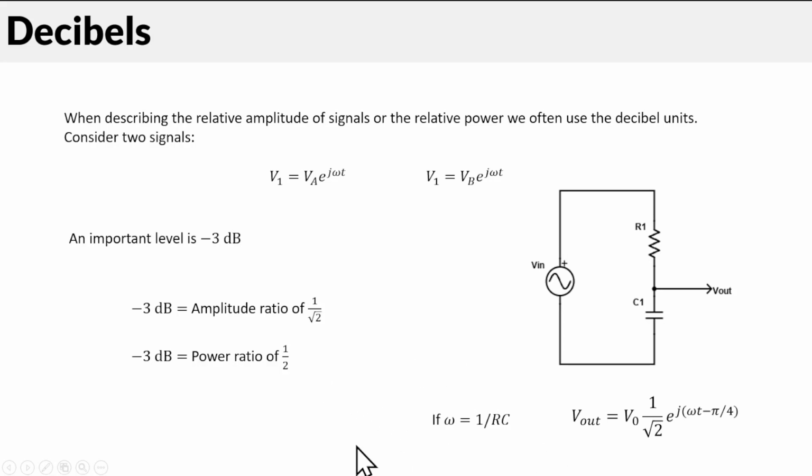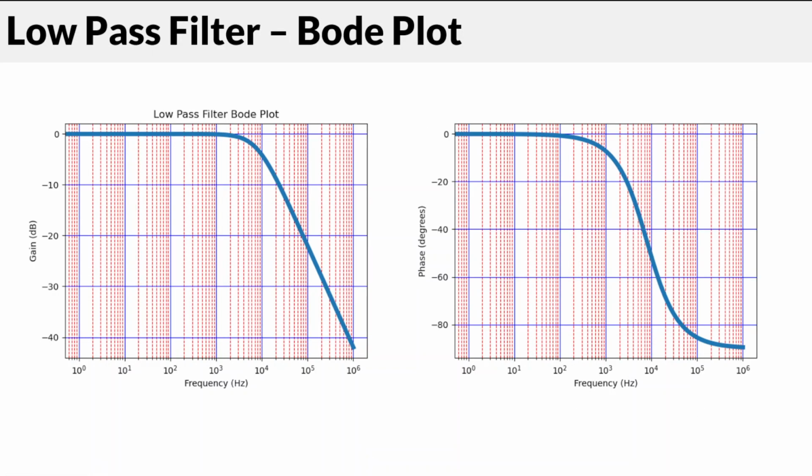So if we plot that on a log graph now, we get what's called a Bode plot. The idea of a Bode plot is you're showing gain and phase together. We'll make some more Bode plots as we go along. We're plotting what we call the gain, the decibel logarithmic ratio of the two signals. We plot these two things versus log of frequency, and we get this very distinct shape.